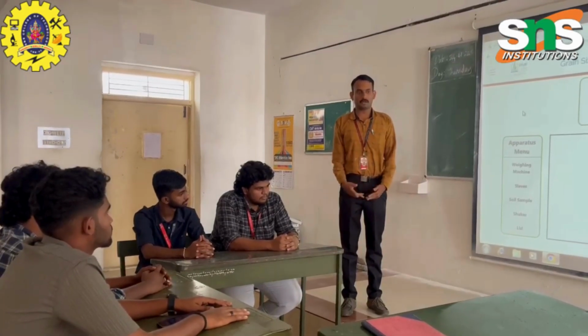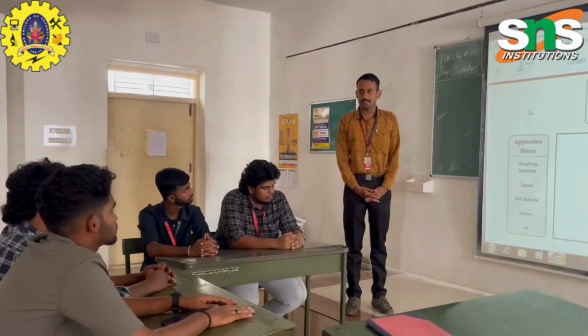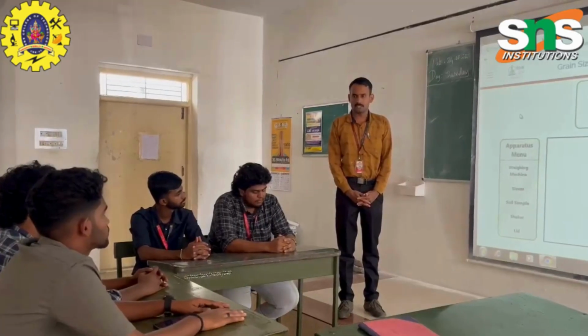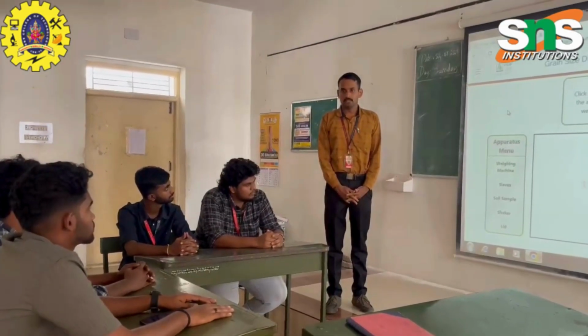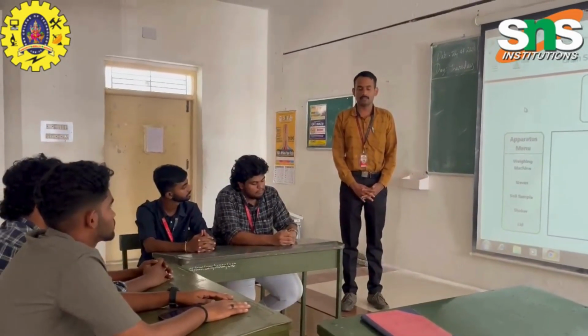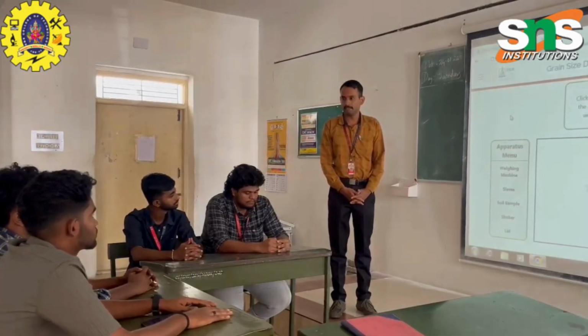In order to ascertain whether the soil is well graded or poorly graded, Sieve Analysis is one of the important tests in finding out the gradation of soil. After performing the Sieve Analysis test, we can find out whether the soil is poorly graded or well graded.